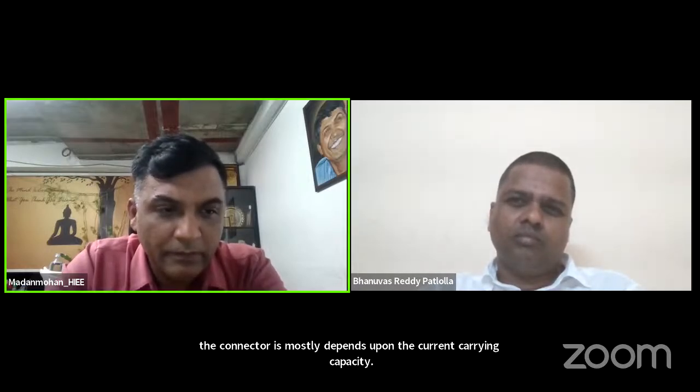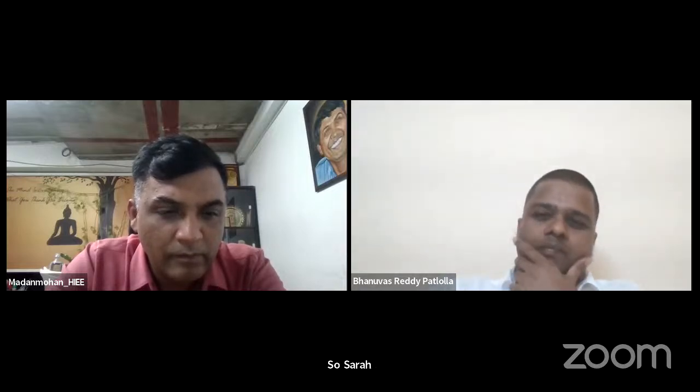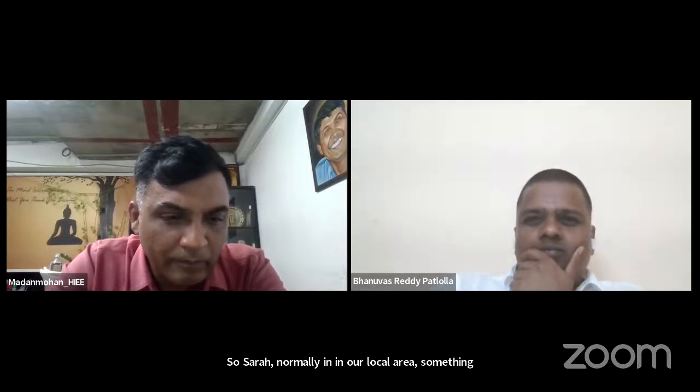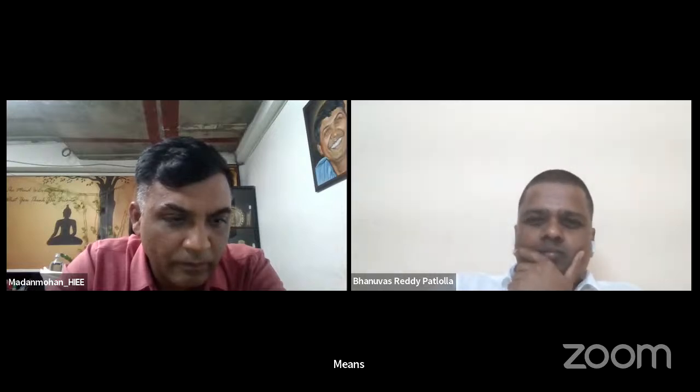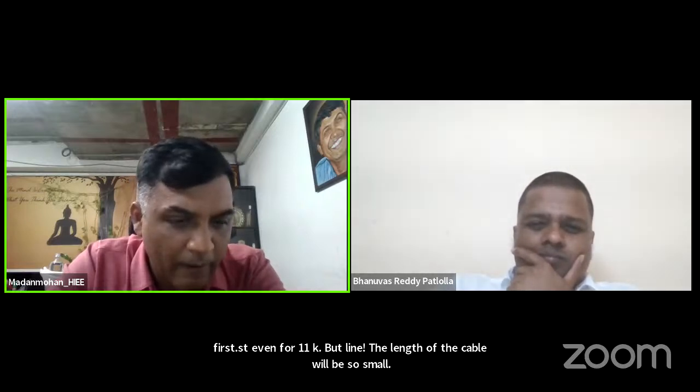Because the conductor size mostly depends upon the current carrying capacity. Yes. So, sir, in our local area, even for an 11 kV line, the cross section of the cable is so small. But for 220 kV and 400 kV, we use bundle conductors, and they are much thicker than the 11 kV cables.